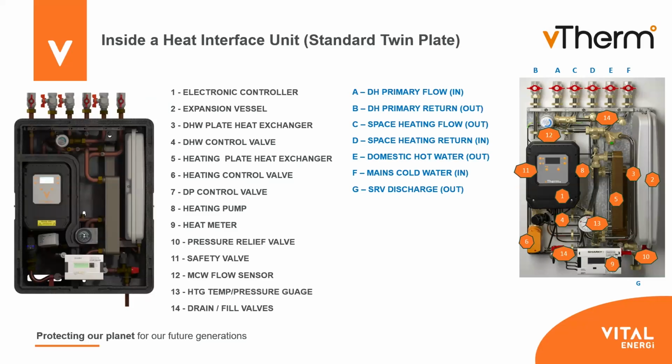And one of the things, as I mentioned, you'll see on this unit, compared to the one on the right-hand side, is that we've now got filter valves. So where we would have had to drain down a HIU to clean the filters out, and this is quite common in the industry, one of the things we've now developed is these filter isolation valves. That means when we isolate, we only now remove a thimble amount of water, and that also helps when we do introduce it back into the system after we've cleaned. We're not adding air, which is bad for the system, and also we're not weakening any inhibitor water as well.